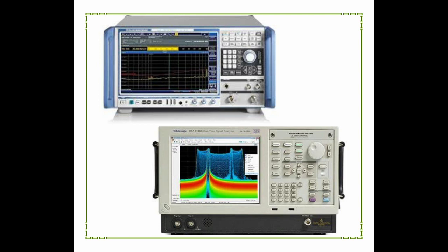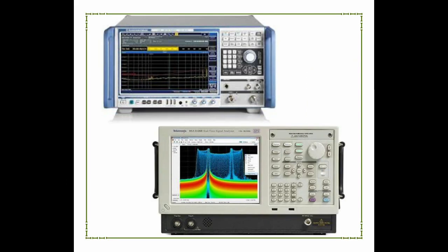We are going to discuss the display of a spectrum analyzer, which has frequency on the horizontal axis and amplitude displayed on the vertical axis. In EMC tests, the measured spectrum is used for basic pre-compliance testing. However, it cannot be used for full EMC tests and measurements for certification. Instead, an EMI receiver is used.